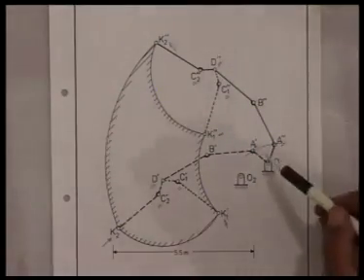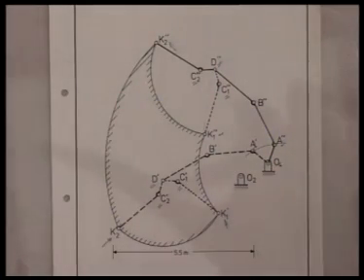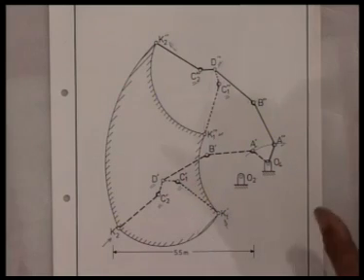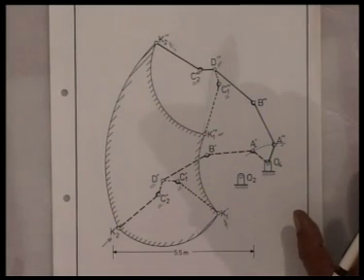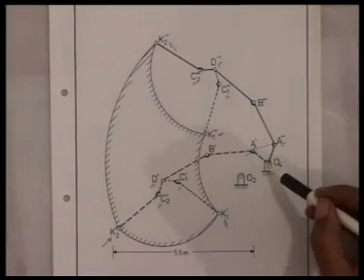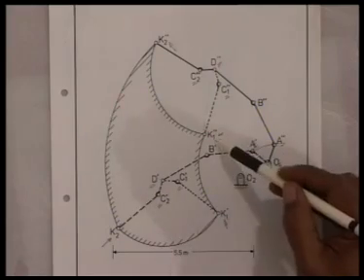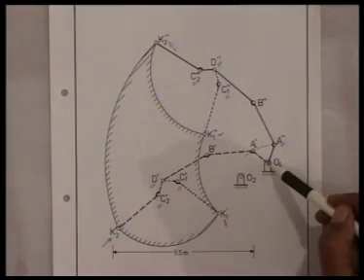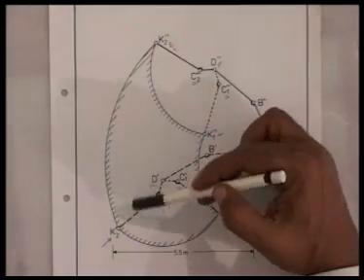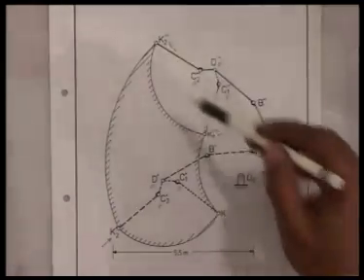In the same way, one can say that the distance from O4 does not change, again because if the actuators are at maximum locations, links 4 and 7 get rigidly connected and K moves on a circle with O4 as center. So, this is another circular arc joining K1 double prime and K1 prime with O4 as center, and another circular arc with O4 as center and radius O4K2 prime.